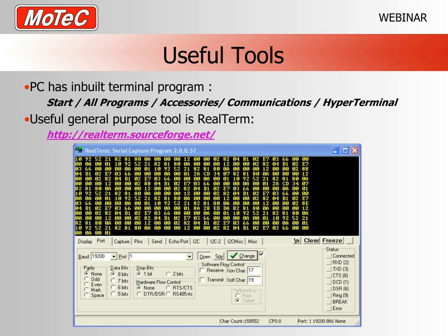Normally this would be showing you exactly how many characters it's received, and you may recall that characters per second is a divided number which is based on the bits per second, approximately divided by 10. So if this port was running at 19,200 and we're running basically a normal data stream out of an M800, we would expect to see roughly 1,900 characters per second at maximum. So this is a useful tool just to establish the veracity of your data before you plug it into the other device that you may be looking at.